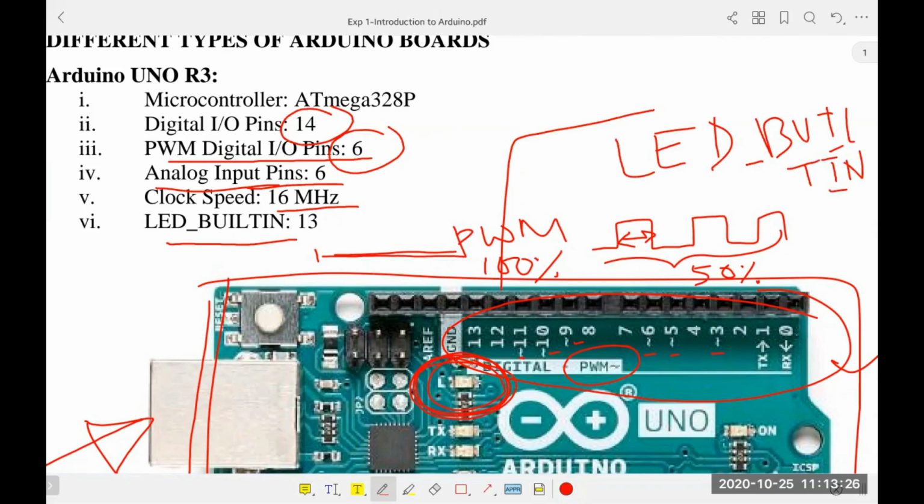That's why in our previous circuit we connected an external LED, since in our Proteus we don't have the built-in LED. Proteus is just giving some simulation facilities, and it is not the full Arduino board. So that's why the built-in LED is not shown in the Proteus environment.